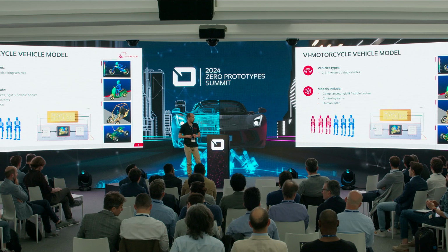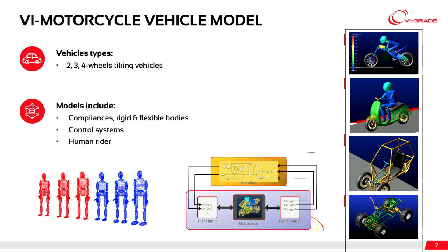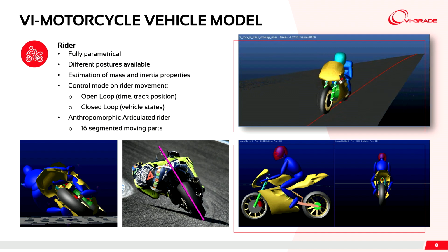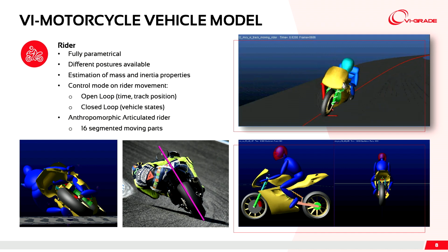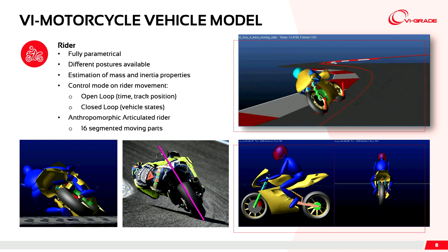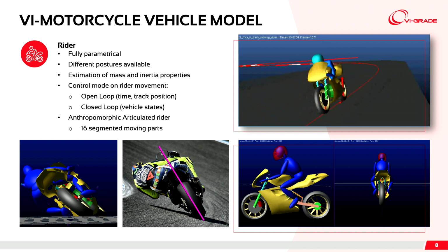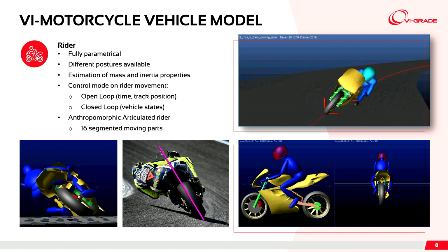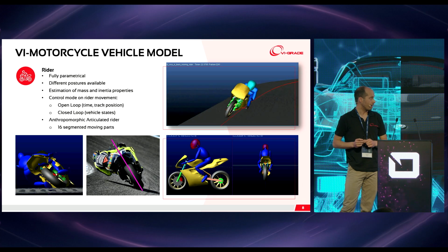to ride the bike. So when talking about the rider, we have the VI-Rider algorithm that rides the bike, but also a rider model, a rider subsystem that is a mass or more masses, moment of inertia, and stiffness in case, because the rider, as you know, is a very important component of the motorcycle, and most of all, it's not fixed with the bike, but it moves with the bike and changes the bike dynamics.